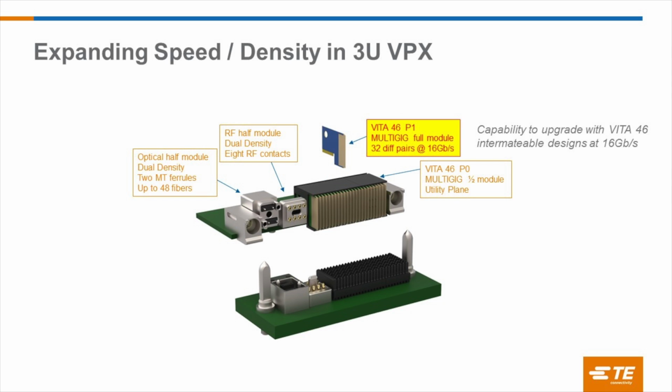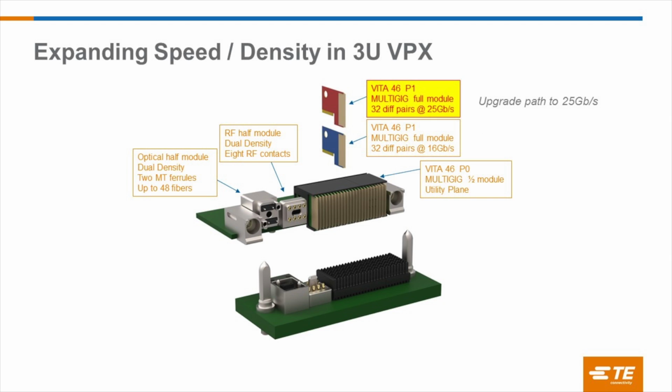And the VPX connector itself. So we talked about some of the roadmaps getting to 16 gigabit per second. We've got designs there now. We're starting to tool initial testable prototypes that, through the wafer development and through some board termination, we're able to achieve 16 gigabit per second. So that will be coming very soon. And then the next tier, 25 gig.